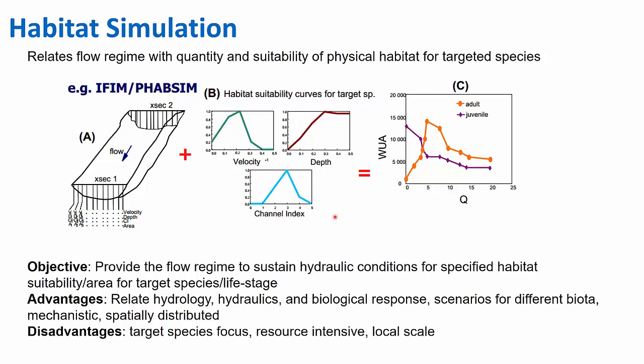Not only think about the different levels of water, but how will be the distribution of velocities and depths given those different flows. So that will be this portion here associated with that distribution. So if of the entire channel that was inundated, how much of that portion was very low flows and very low depths, or large flows and large depths. Those can be associated with preferential curves.